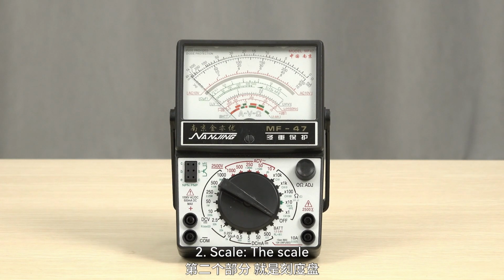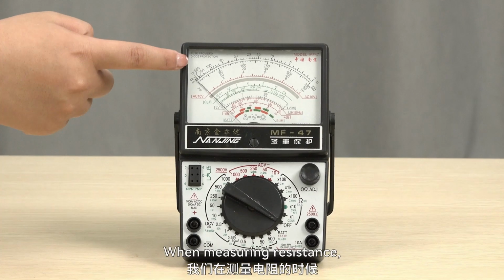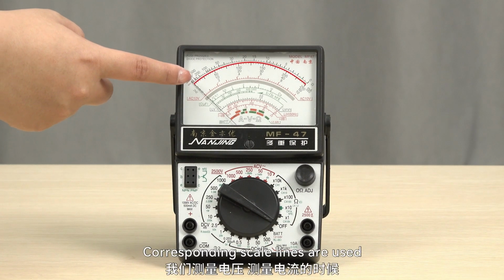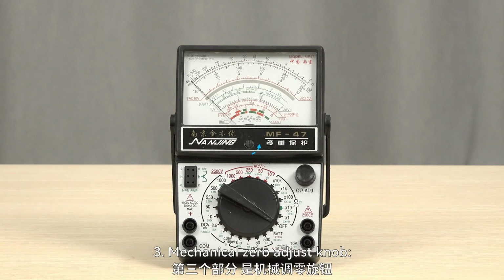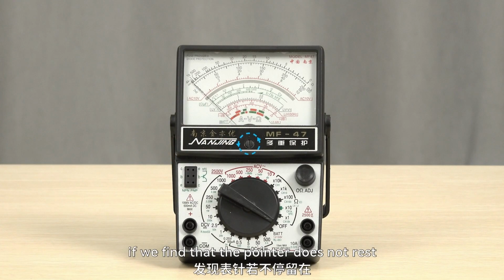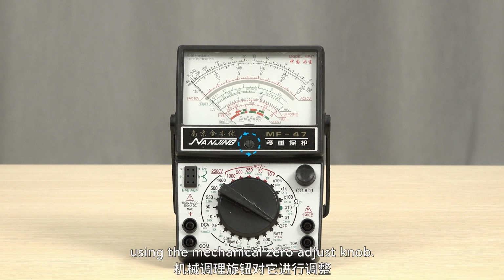2. Scale. The scale is marked with numerous lines, each serving a specific purpose. When measuring resistance, we use the topmost line, the first one. Corresponding scale lines are used when measuring voltage and current. 3. Mechanical zero adjust knob. Before taking measurements with an analog multimeter, if we find that the pointer does not rest at the zero mark on the left, we need to adjust it using the mechanical zero adjust knob.